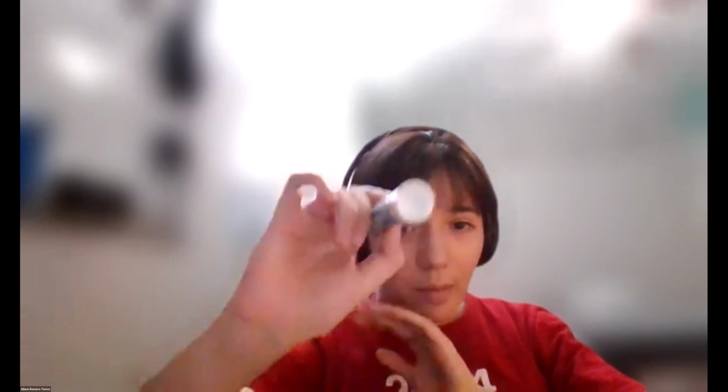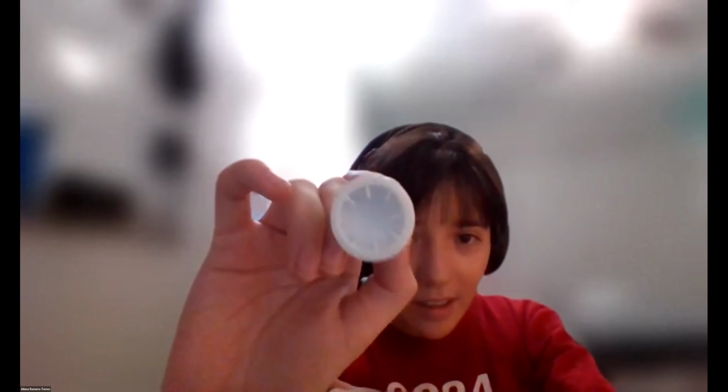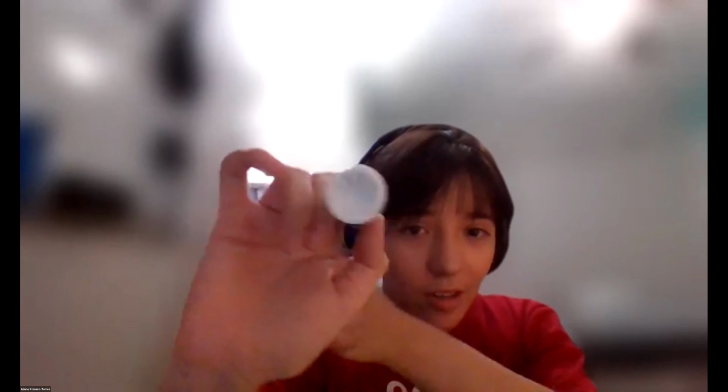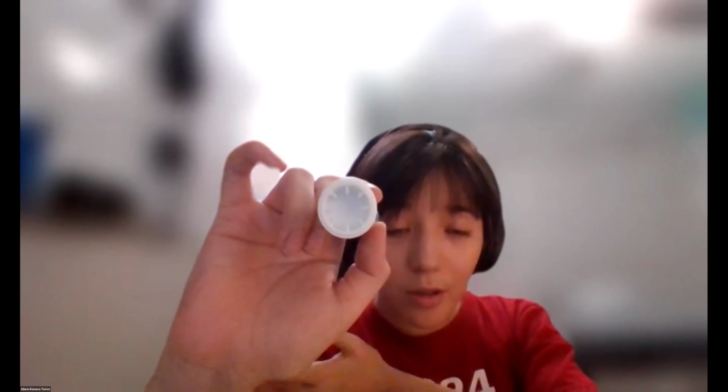If you are done with your marker, I would recommend trying to look at ways to make it more realistic. Like at the bottom of a real Edgestone marker, there are these ridges, and you could try doing that by using the remove option when you extrude, or making the tip look more beveled inside, or also hollow here. So if you're done, those are several ways you can try to make it better. Or if you need help, you can definitely let me know.